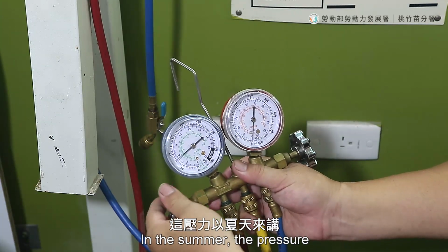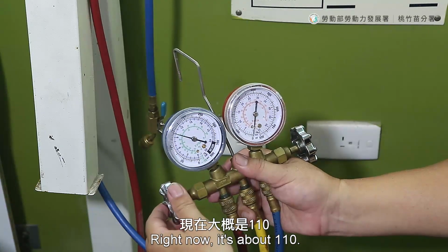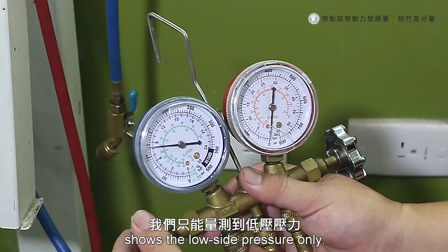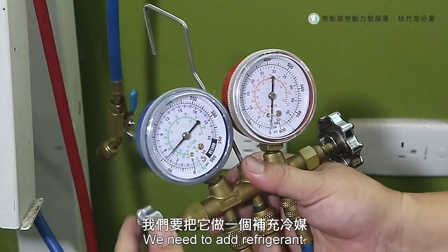In the summer, the pressure should be around 120 to 130. Right now, it's about 110. This split-type AC shows the low side pressure only. We can conclude that there's a slight shortage of refrigerant. We need to add refrigerant.